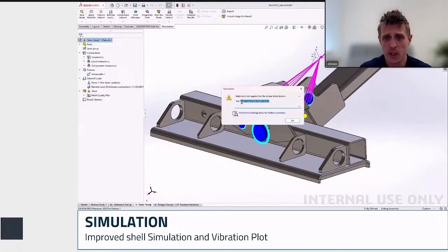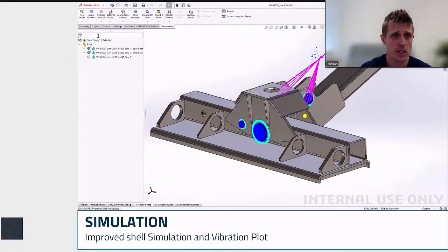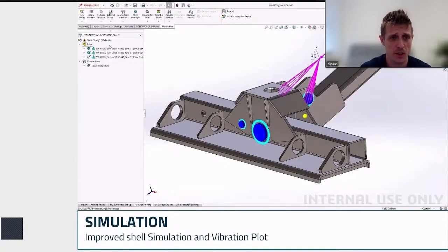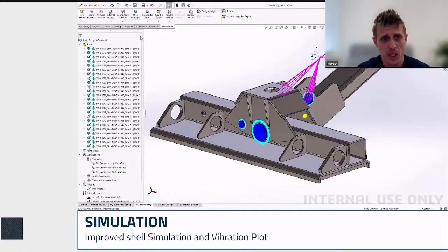So with the load applied from the coordinate system to the pin, we'll go ahead and click run, but unfortunately we have an error. Apparently one of our components is missing a material, and from 2026, SOLIDWORKS will now very helpfully explain which material is missing from what part. We'll just go ahead and reattach some material, a plain carbon steel, and then run the study again.